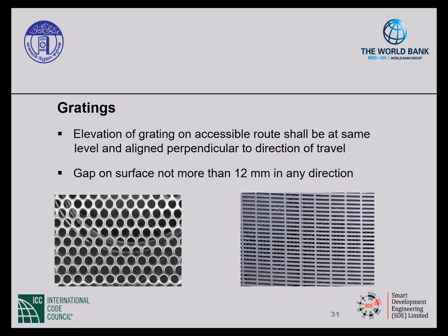So what's the hazard here? If the opening is too large, the wheel of a wheelchair could get stuck and cause it to tip over, which would cause injury to a person. Or maybe if you're using a cane, the cane could get stuck and the person could fall.